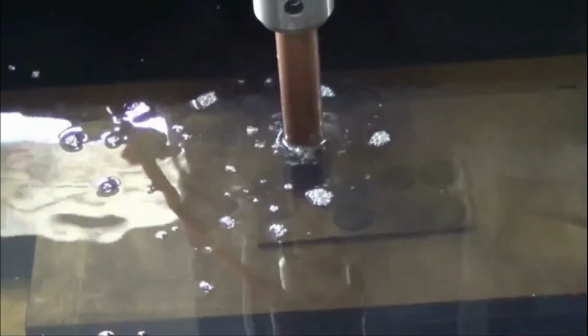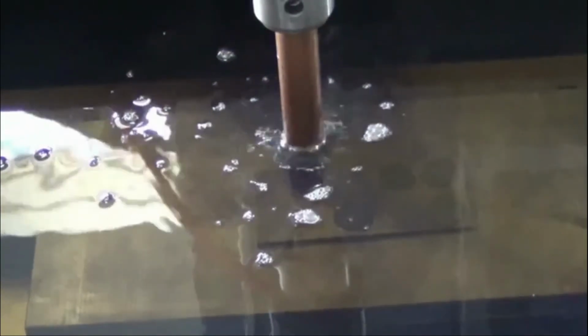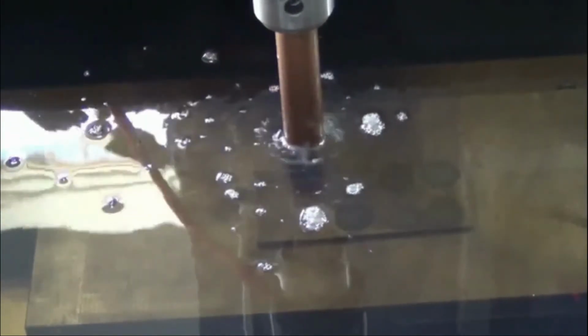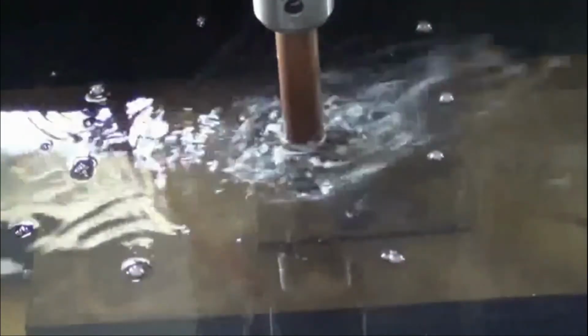Here, both the electrode and the workpiece are submerged in the dielectric fluid, due to which a spark takes place in the gap between the electrode and the workpiece. Due to this, a high temperature is produced in the region between the workpiece and the electrode, due to which a certain quantity of material from the workpiece starts melting and is removed or separated from the workpiece surface. So this dielectric plays a very important role.